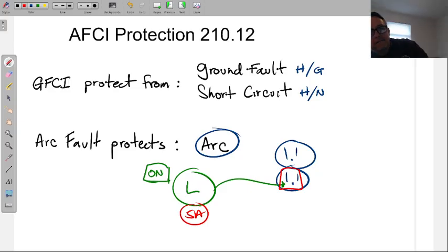So we just never use normal ones ever? Never again. Even though you can buy them, and I buy them and I install them. Yeah, you have to have AFCI in residential. The reason why they sell the other ones is because commercial buildings don't require that. So that's the cheaper one. Yeah, and it's cheaper. You go to the box, they're 89 cents. I'm not going to go buy that $5 one.